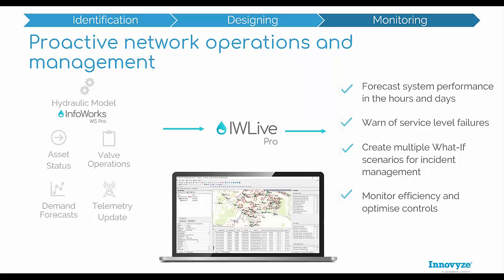So again, using that pipe break tool that we talked about earlier, that functionality is available within this live environment. We can select a pipe, we can specify the parameters of that burst or that leak, and in real time we can see what effect that will have on the network and on customers, and then more importantly, how we can deal with that. So does that pipe need isolating? Which valves do we need to select? And since that is then isolated, are there other things within the network we need to consider?